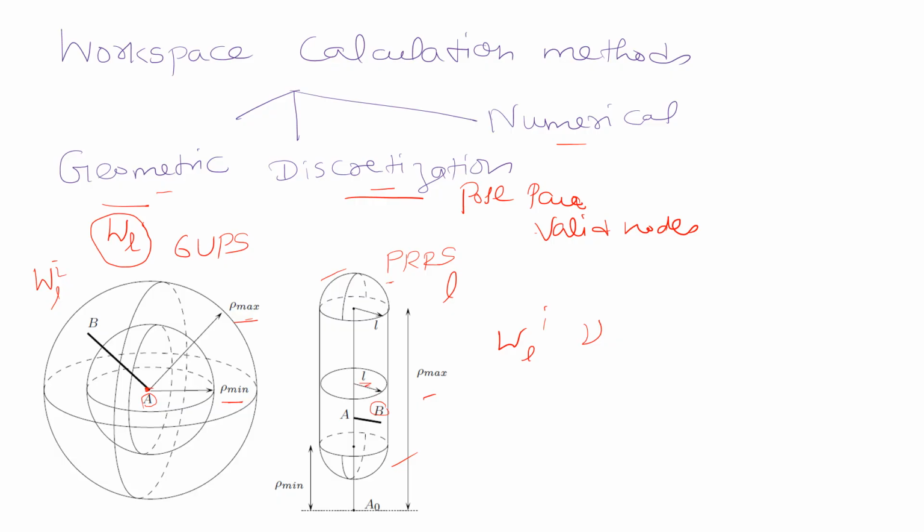The advantage of this method is that it allows one to take into account all the constraints, in contrast to the geometric approach. But it also has some drawbacks. The accuracy of the boundary depends upon the sampling step that is used to create the grid, and the computational time increases exponentially as the sampling step decreases.